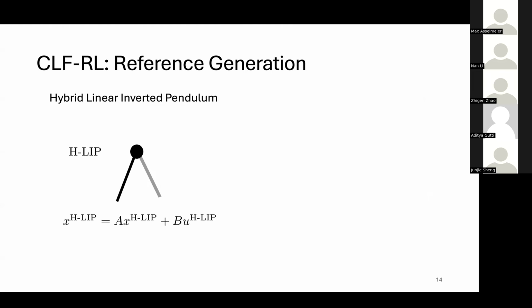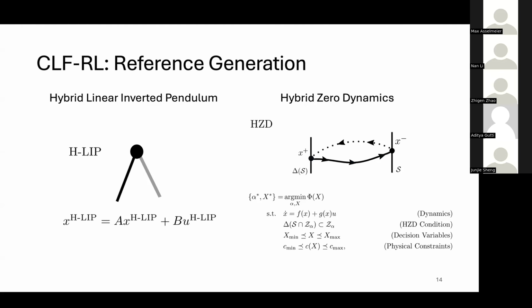I'll show you the video of this one later, but it looks kind of like you might expect a linear inverted pendulum walking robot to look. If you've seen a LIP controller before, it kind of looks like that because we're telling it to mimic this. Then the other one we looked at, and this is from the video you just saw, would be our, I'll say, hybrid zero dynamics inspired approach. I think inspired is the correct term because we're not doing true hybrid zero dynamics. But hybrid zero dynamics was a methodology that was more prevalent.